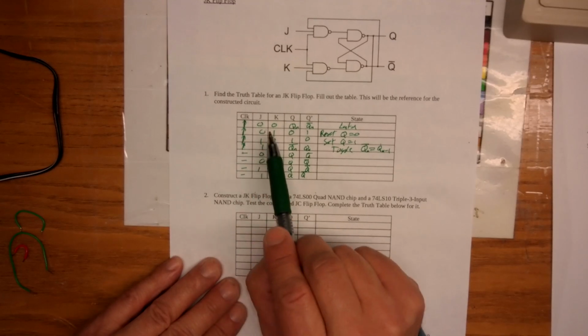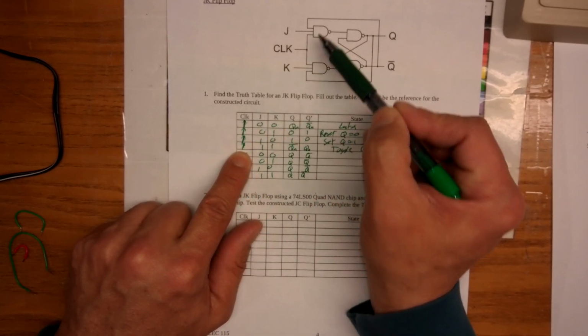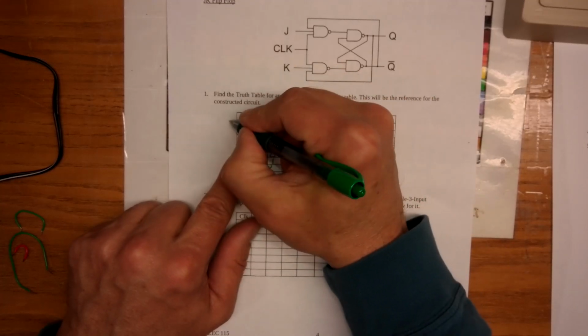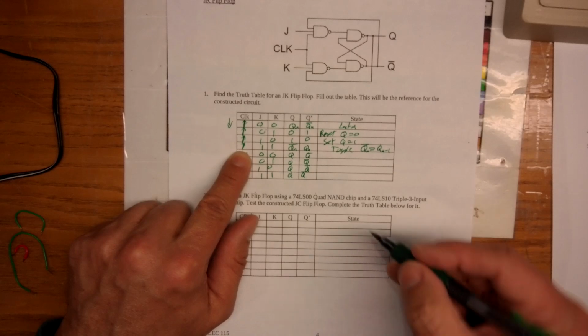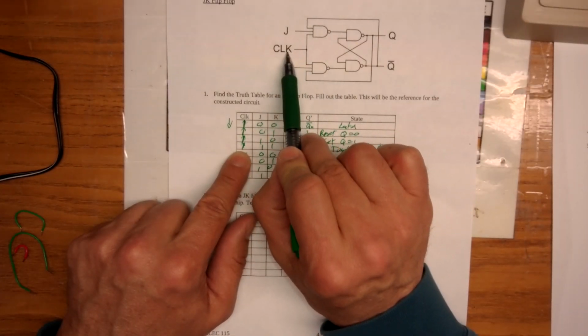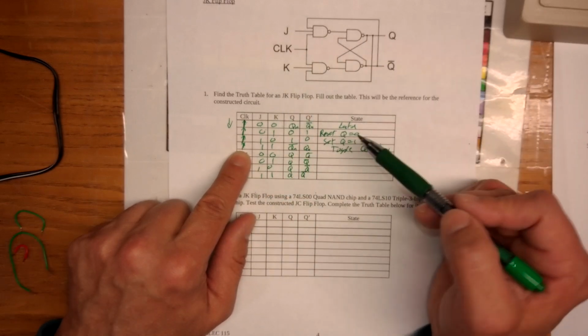All they're recognizing is this is my truth table for JK when the clock goes to trigger it. A lot of times they'll show an up arrow, which says it's going on the positive edge. A down arrow is on the negative edge. Ours is actually, while we drew this as a clock, this one will actually work as more of an enable, which means if this is 1, stuff happens. When it's 0, stuff won't happen.